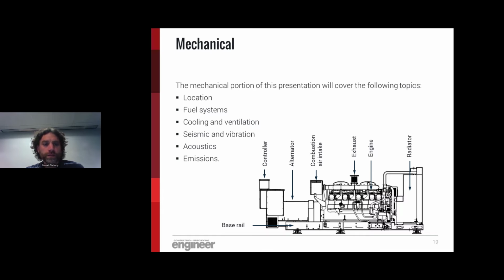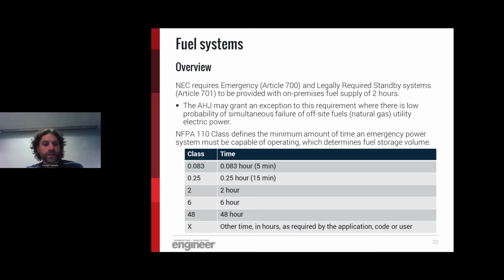We'll move on to the next slide. So getting into some of the fuel systems for the engine generators. As Brian mentioned previously, the NEC requires, under Article 700 for emergency systems and legally required standby systems, that they be provided with fuel for a minimum of 2 hours. That means on-site storage: the fuel is literally there on-site and isn't off-site.